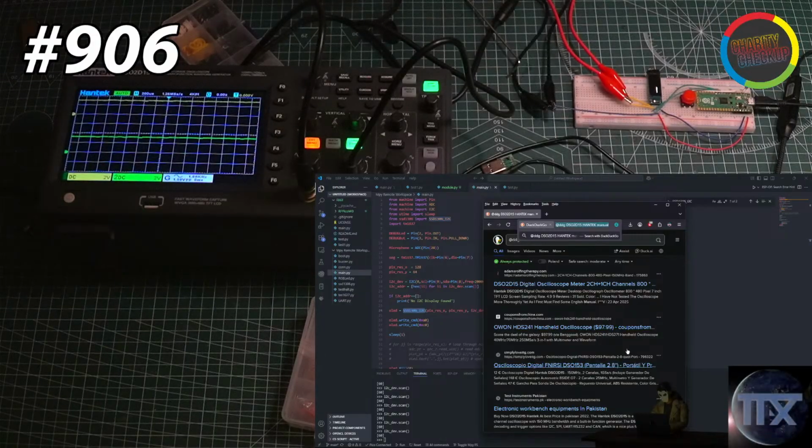So you can set up a hardware trigger, like a one pin signal from the Raspberry Pi, that will trigger the oscilloscope to stop there. Isn't that kind of cool? That is really useful. I don't use this feature very often, but it is a very important feature, and I'm all self-taught, so I don't specifically know.